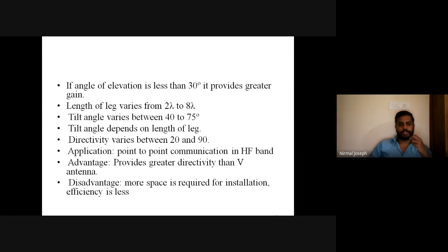Tilt angle depends on the length of the leg. Directivity varies from 20 dB to 90 dB maximum. Then the application: point-to-point communication in the high frequency band. The advantage is that it provides greater directivity than the V antenna. That we can justify from the figure itself.